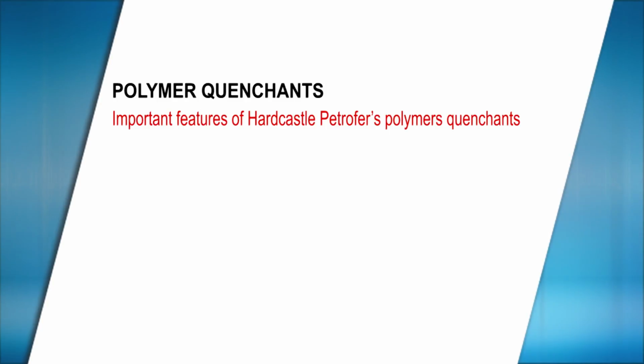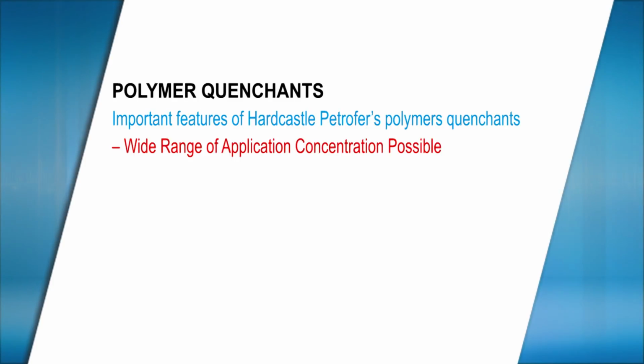Hardcastle Petrofer has rich experience of formulating and manufacturing polymer quenchants. The wide range of polymer quenchants available provide the users the choice of options to suit their performance requirements. These polymer quenchants can be used in a wide range of concentrations in water. This property provides the users with the flexibility to use the same polymer for quenching of a variety of steel grades and also for use in induction hardening as well as tank quenching applications.